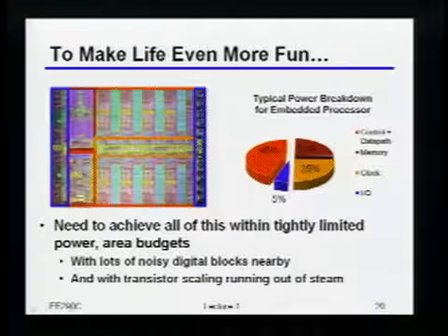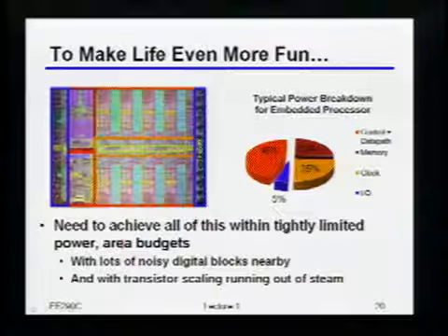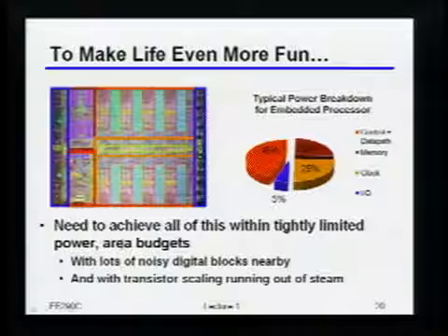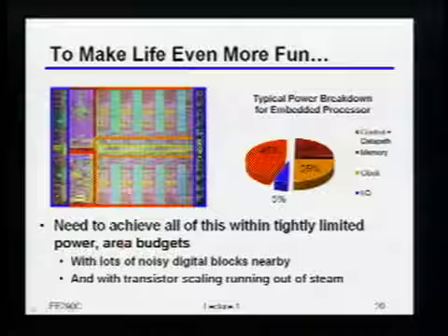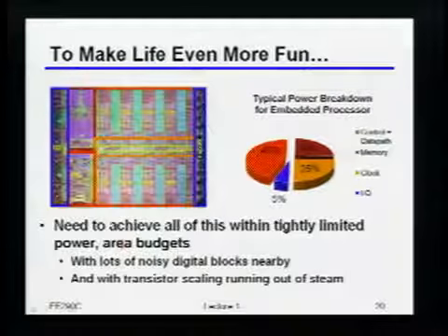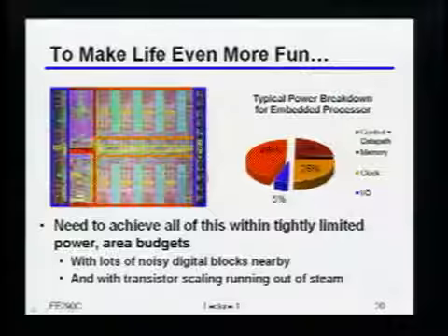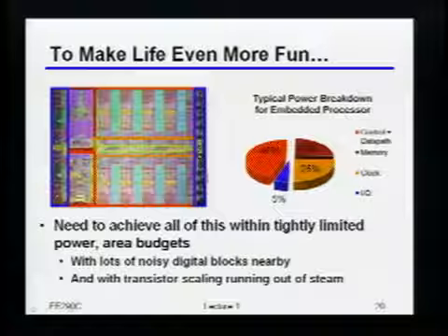That entire rest of the thing right there, which, by the way, dissipates about 100 watts or so, that's all some big, nasty digital block that likes to do whatever the heck it likes to do and creates a couple hundred millivolts of noise on the supply, and can easily create volts of common mode variation between different points on the board, and so on and so forth. Okay? So the message here is that it is actually a pretty tough thing to do.